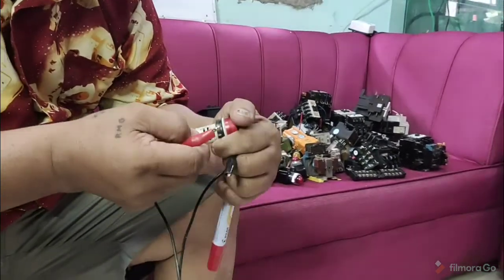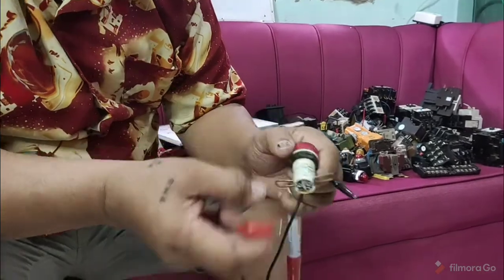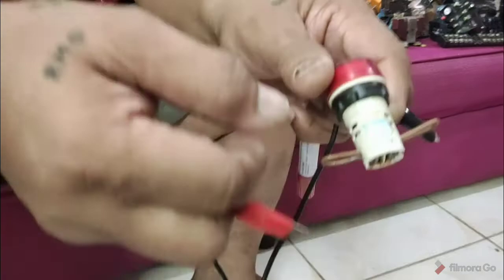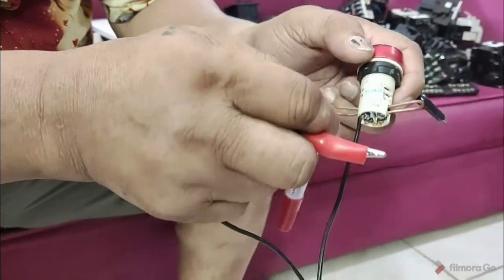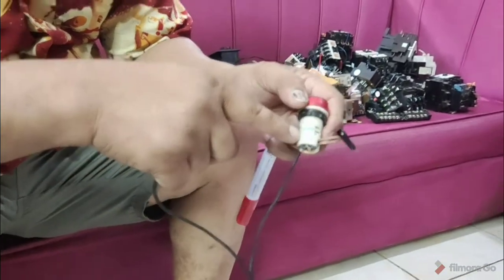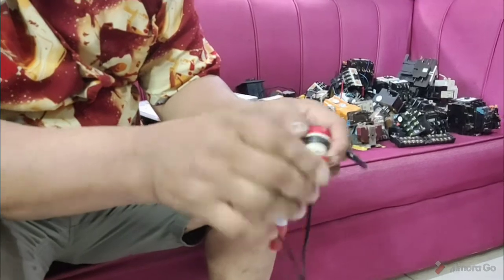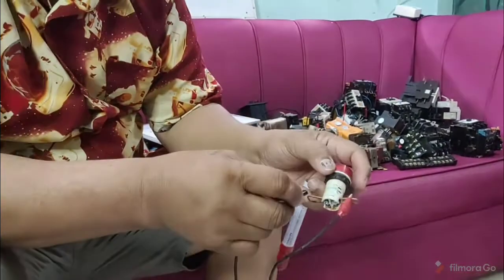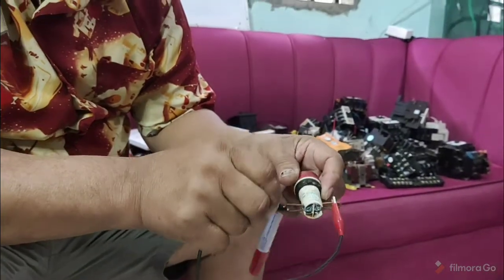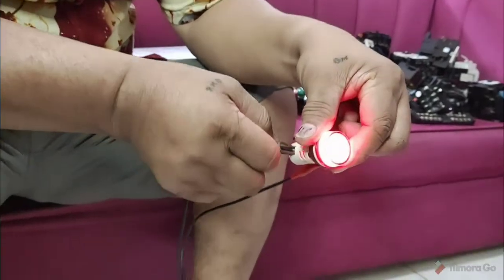make sure that the voltage here is rated 220 volts, because there is a caption here. Not all are 220, because there are also indicating lamps that are only good for 12 volts or 6 volts. So make sure that you can see the caption here where it indicates 220 volts. Then you can immediately connect this to 220. If it's still good, then it will come on. Here, it lost contact. Look at that. So you have that.